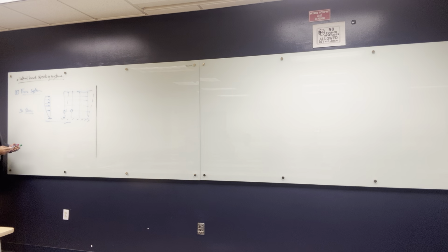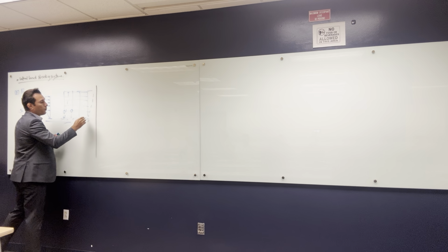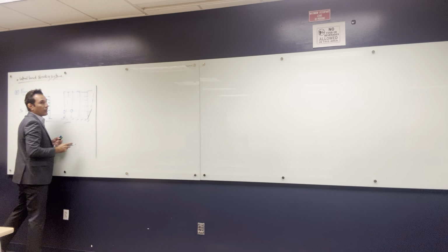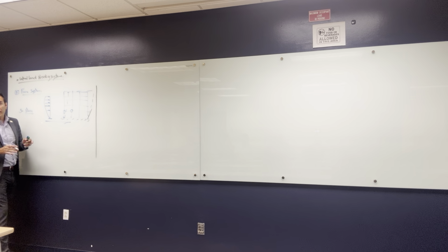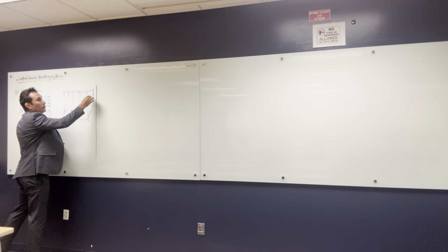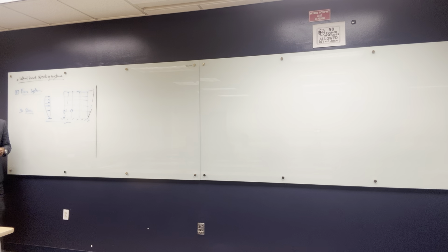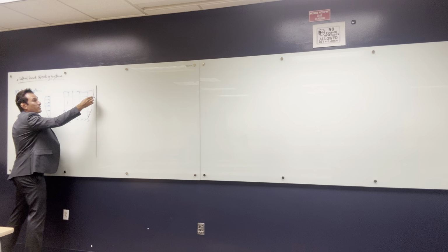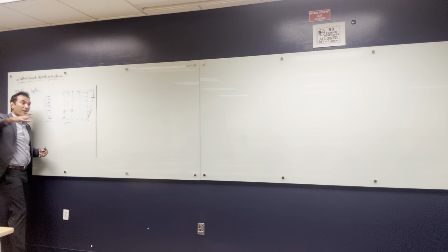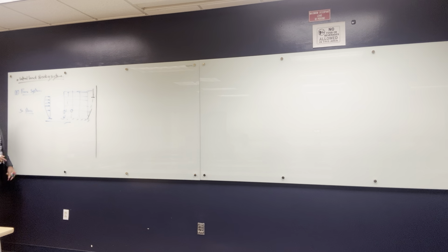And do you guys remember when we talked about this system, we talked about the slope, right? We said that the slope of this system is big at the base, but when you go up, the slope is less. And we talked about the interstory drifts, and we said that this system is very good in the upper stories, and the lower stories is not that good.